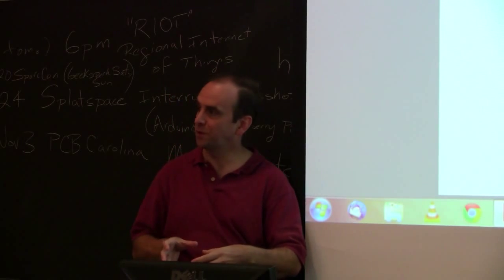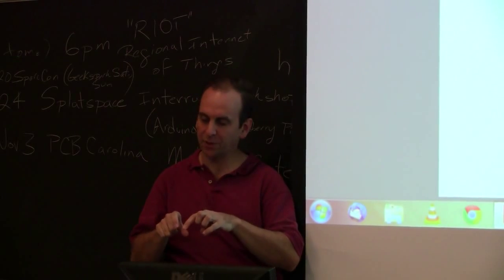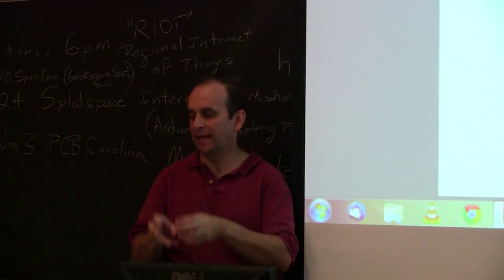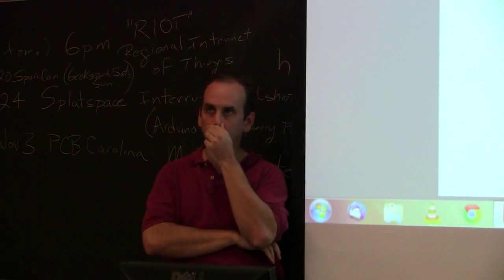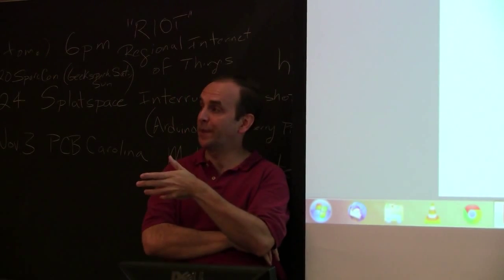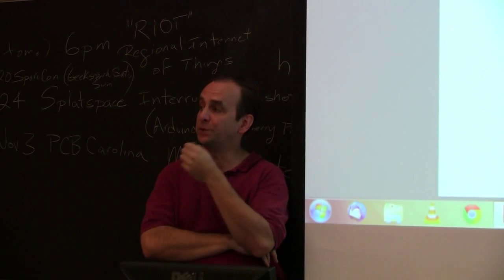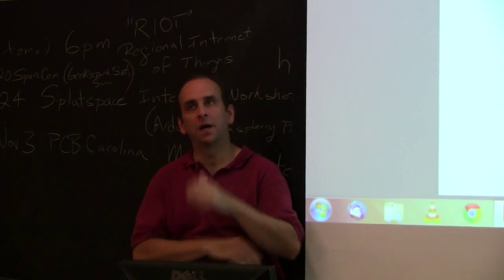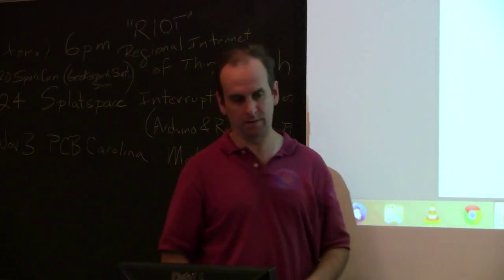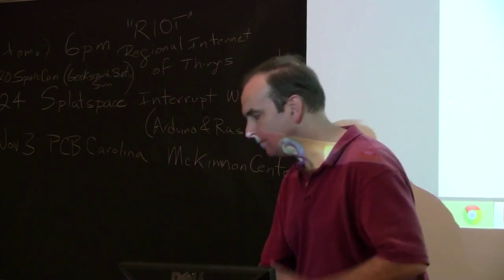Generally on a larger package, there's more space, so they're able to do better packaging things. They can actually orient at a physical level, so they can create a capacitor that has lower parasitics. So if you can tolerate the space and everything else being equal, then usually it's a good idea to use the bigger package. What are parasitics? Parasitics? Okay. Let me go back to the last issue.